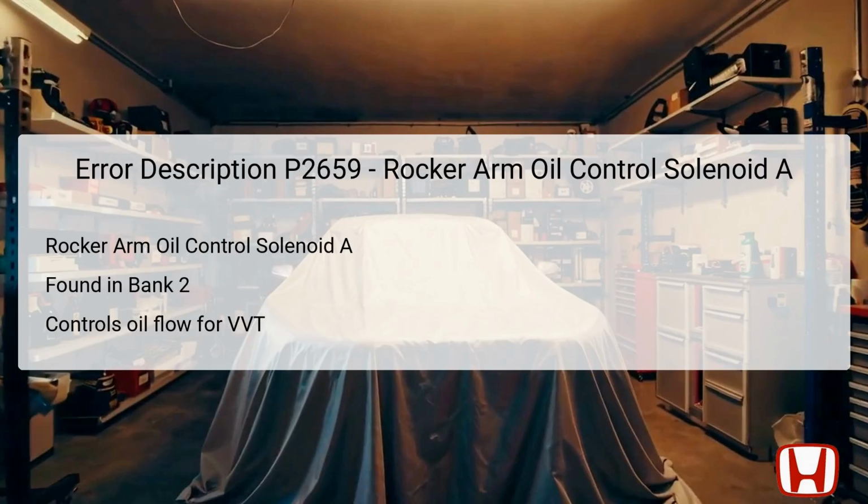DTC P2659 highlights an issue with the rocker arm oil control solenoid A, specifically on bank 2 of the engine. The solenoid is crucial for the operation of the variable valve timing (VVT) system, which adjusts the timing of the engine's valves based on driving conditions. Located near the cylinder head, it regulates the flow of oil that controls the position of the rocker arms, thus impacting engine performance and emissions. When the circuit voltage is too high, it can lead to erratic valve timing, resulting in poor engine performance.